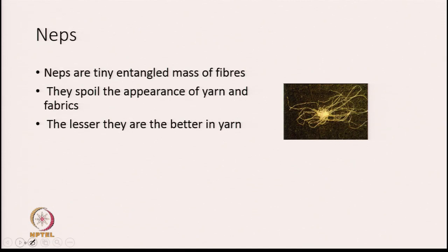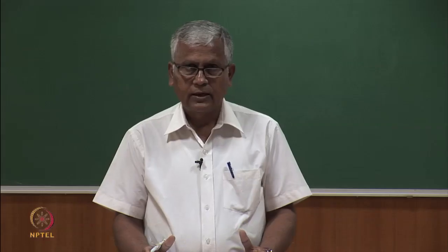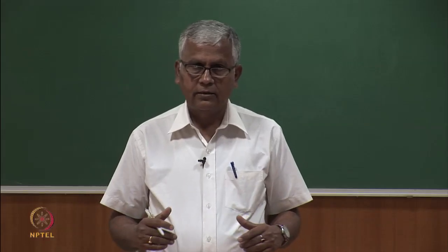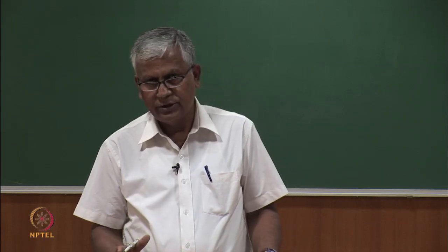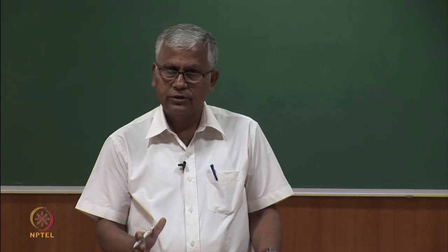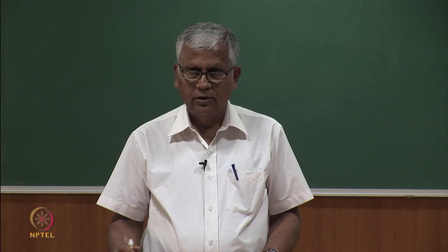And carding is a process by which NEPs can be removed. We can eliminate many NEPs. At the same time, we must know that carding can also generate NEPs. So, carding is a machine which can generate NEPs, and which can also remove or eliminate NEPs.